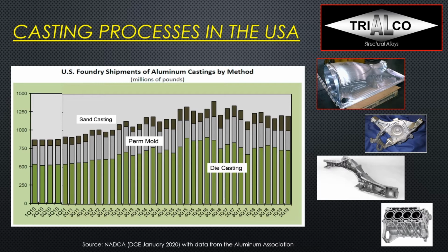So that's a longitudinal member of a car body structure. This would be a very thin-walled part, about 2 to 3 millimeter wall thickness. And it's also very long and a pretty big casting, which we will see later again in a different webinar.